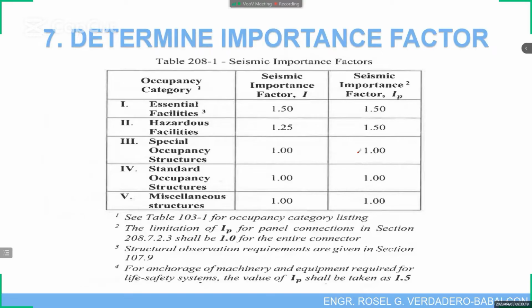So using the importance factor, it is 1.5. The importance factor is a multiplier to the computation of the base shear. So multiplying the base shear by a value of 1.5 will increase the amount of base shear by 50%. That is the computation assumed by the code to consider in terms of the risk, and also to add strength to our structure.